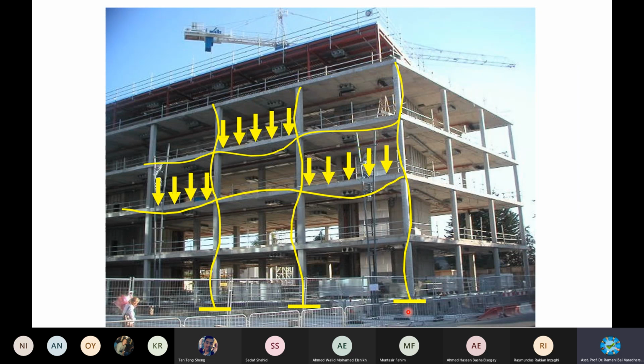Due to this loading, start from here. This is a foundation, a basement. This column is supported by this basement, and the entire loading is acting onto this structure, right? Due to this, it will bend like this, and then like this. If you take the space frame analysis and its result for the frame structure, you will have these types of bending. Here, if you look at this one, it's sagging and then hogging, sagging, hogging, and then sagging, a bit of hogging, and then again sagging, hogging, sagging, hogging. Like that, you have different types depending on the loading.